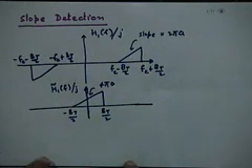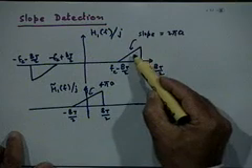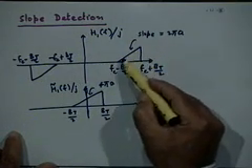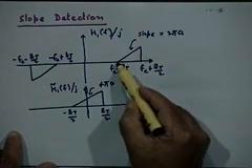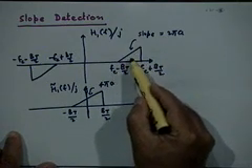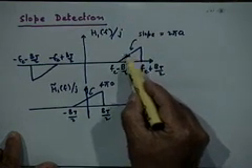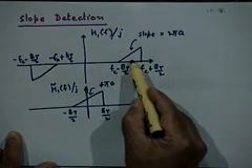If you recollect, we were first looking at this idealized model of the slope detector, which is not that of a balanced discriminator, but that of an unbalanced discriminator. We assumed a slope circuit whose frequency response was proportional to the frequency deviation from FC, going on both sides, but with a non-zero DC response corresponding to FC.